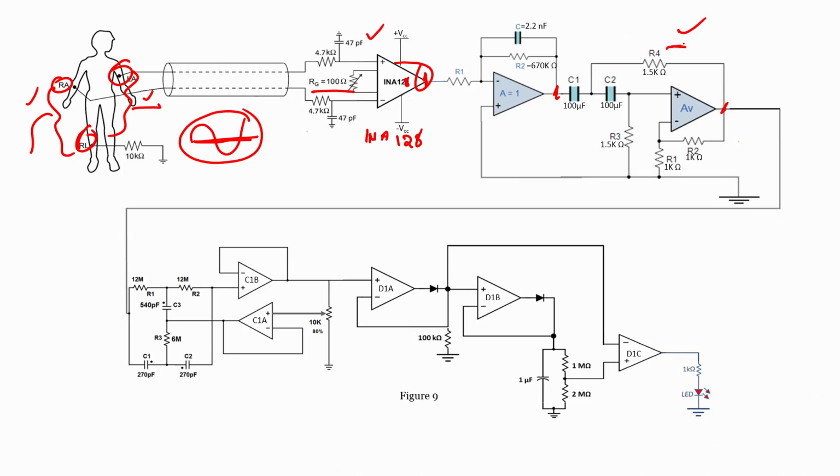Then we also have some odd multiples of our power line interference, which is greater than 100 Hz. By using our low pass filter we are completely eliminating it, and a notch filter removes our 50 Hz signal. We have also seen in the practical, theoretical, as well as simulation versions how exactly this works. So we will only show till this point, because this requires some more computational effort to do the verification.